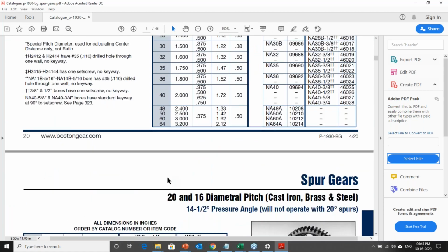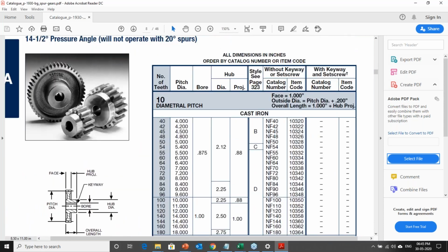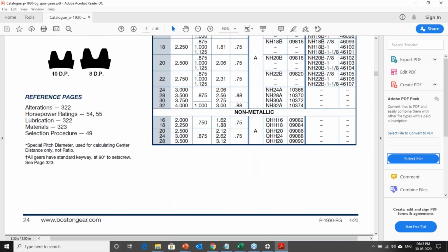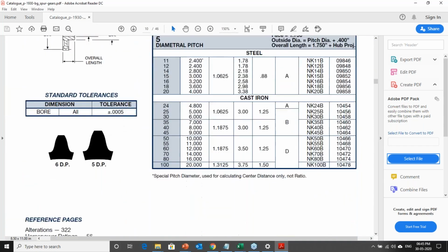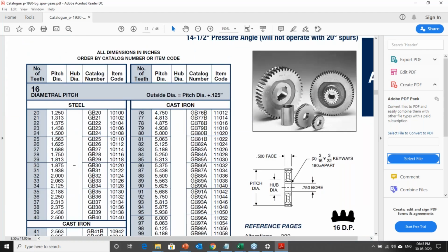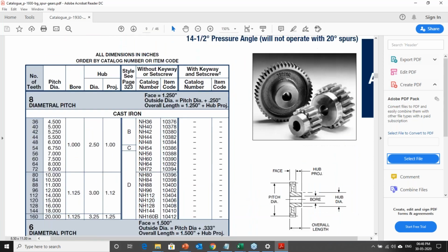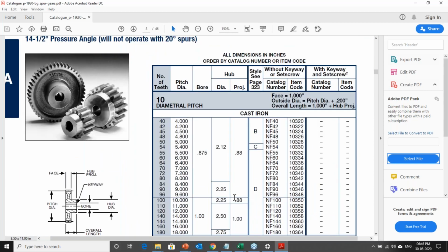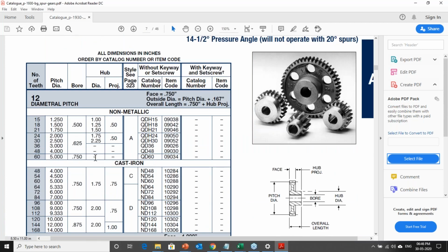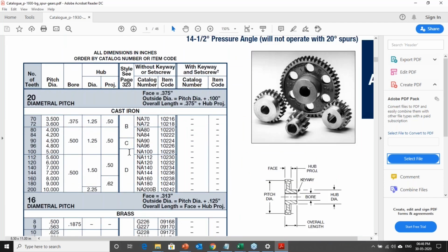So I will do this selection with a gear so that you people can understand this. I'm just checking whether I have the same diametric pitch. It means 2 pi r divided by number of teeth. If I can get it in this catalog, it's okay. Else, we assume this is the diametric pitch where I can get both the gears, one for 3-inch and another for 18-inch. But these dimensions are in, I think it is in mm. Yeah, no, it is in inch.